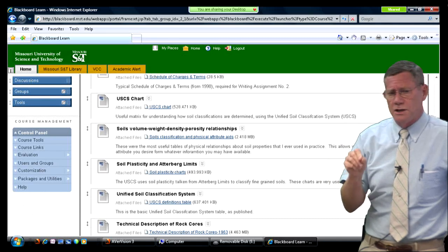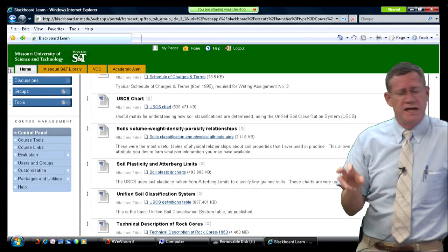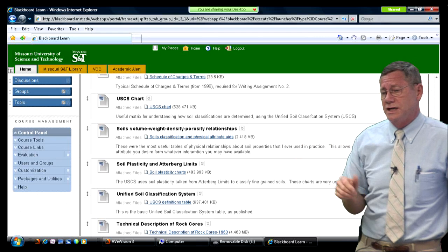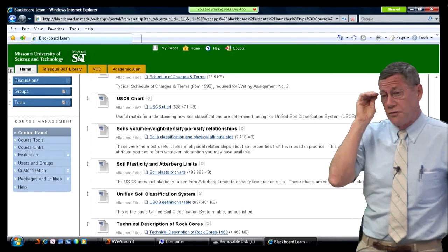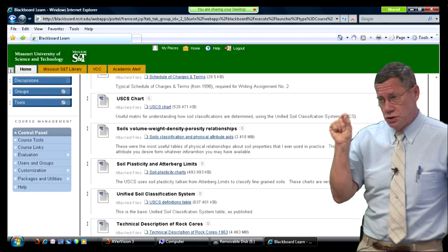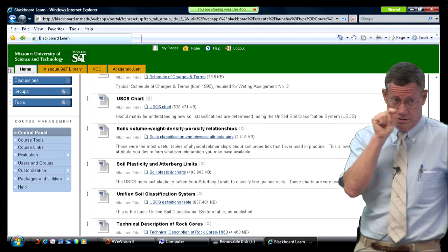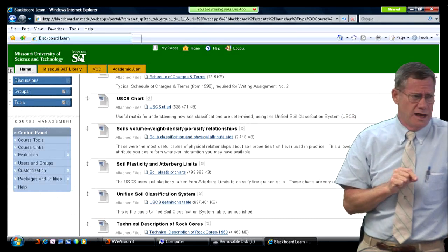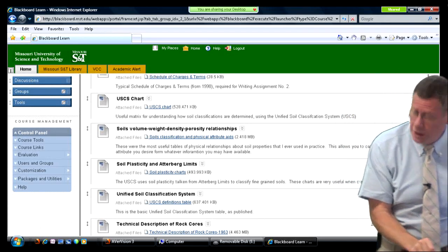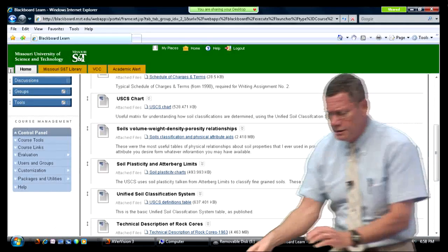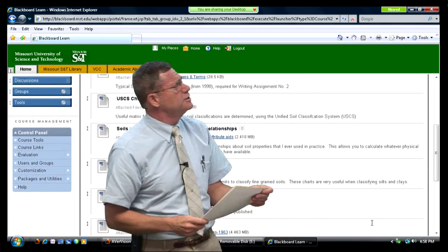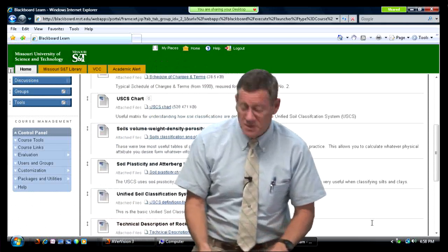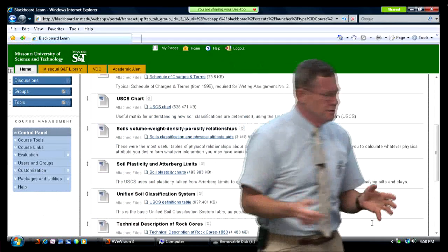That field log is always subject to change based on the laboratory classification tests, which are sieve tests and plasticity indices. And you throw away the field logs. You don't save those, because attorneys will use those to incinerate you on the stand. Because, well, you called this a clay, Dr. Rogers, and over here you're calling it a silt. It's obvious you don't know what it is, do you?